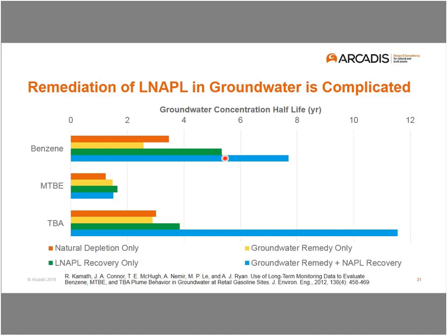which is a bit counterintuitive, but it says that the value of that NAPL recovery, or the NAPL recovery combined with a groundwater remedy, doesn't come out of the statistics; there doesn't appear to be a value. And I think that can be linked back to the conceptual site models, the LNAPL conceptual site model, understanding the source zone so you understand how you're trying to remediate the source zone.